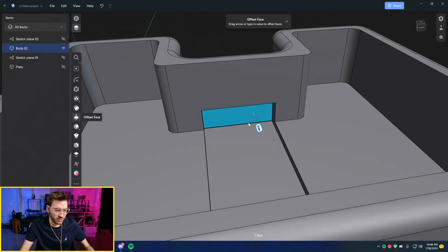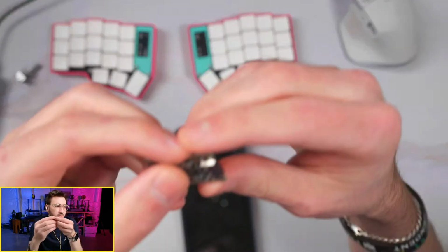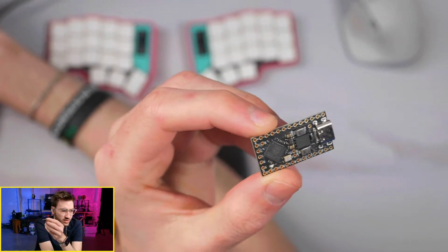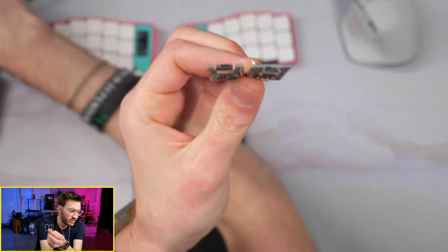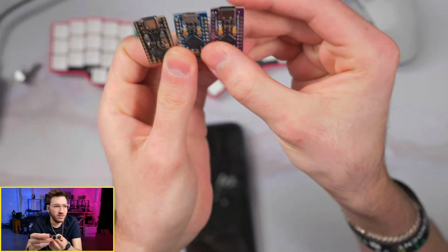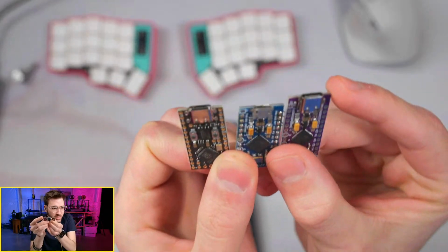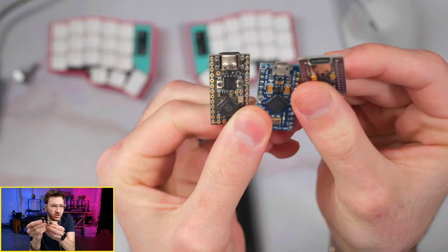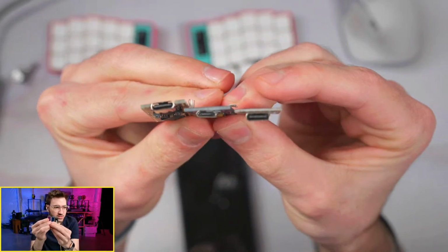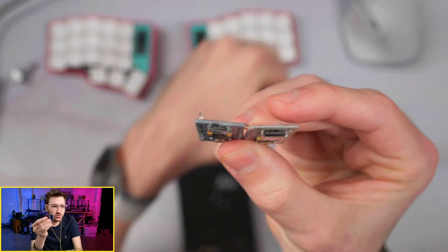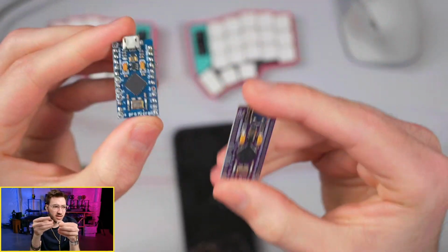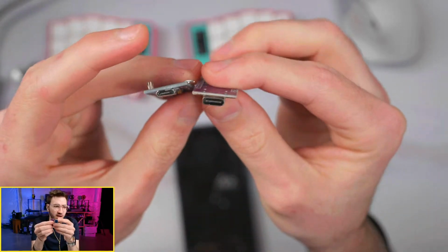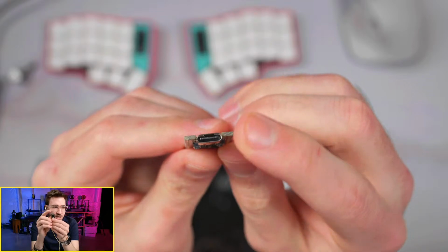So now on this board that I'm using, the little RP2040, if I pull up, so Fortism, this is what I think you were asking about. Yeah, this is what you were asking. We have 3 different Pro Micros here. We have a regular USB-C one on the right. We have a micro USB here, which actually doesn't work. This is a dead board. I killed this one. And then we have the RP2040. The difference is, if you look at those ports, they're all kind of similar height. These two, the micro USB and the USB-C, have the same exact dimensions. You just do the dimensions for the USB-C here, which is fine. This one here is offset by 1.35.